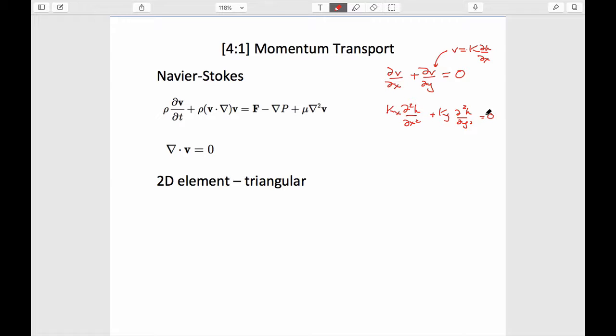We have a conservation equation. We require that the variables in the system are continuous. There's no discontinuities. And we have a constitutive equation. So in this particular case, our continuity equation is conservation of mass. This is just saying mass in equals mass out. And the constitutive equation is Darcy's law, which links the velocities in this equation to some other variable, which is head. And so in this, we satisfy continuity, and we use a constitutive law which accommodates the fact that we have viscous losses in the system.